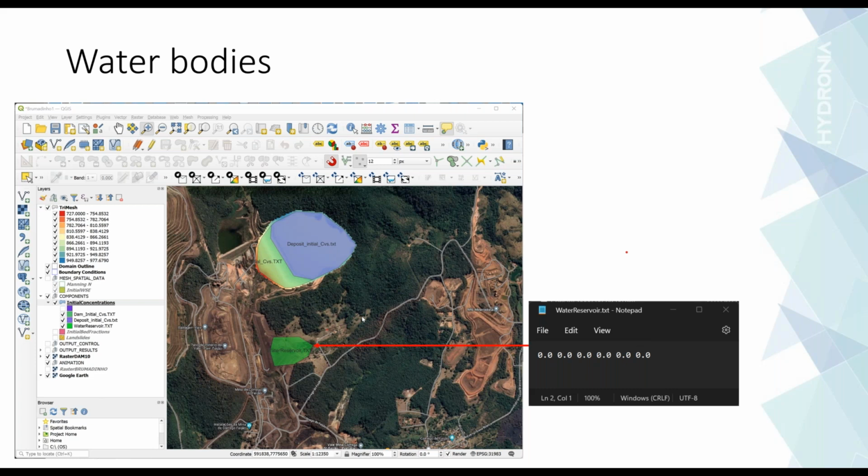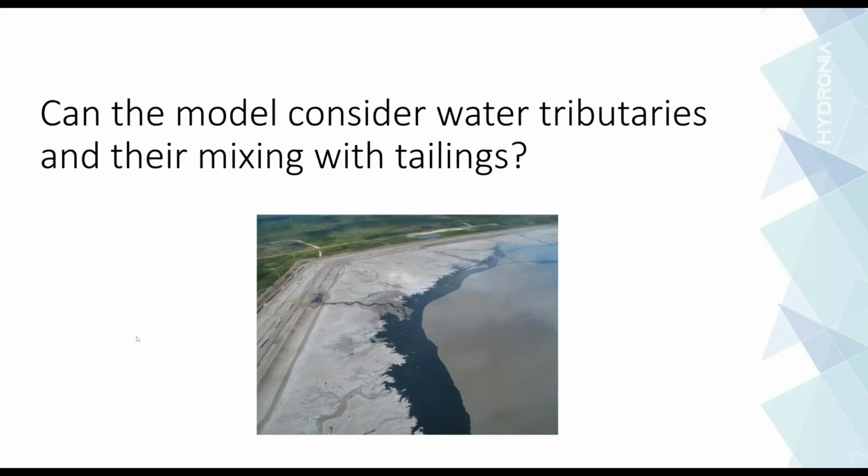So what happens is that you have a rainfall event, and then the rainfall enters your mesh, let's say one cell. That it's a volume added in that specific time step to the point where the rainfall occurs.